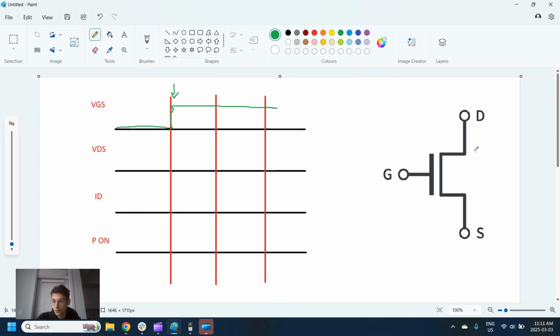And what happens? Well, our voltage here, we would love for this to drop instantly. This needs to go from whatever the VDS is down to 0, because that means a short circuit. And that means the current will also need to go from 0 up to some value and stay there constantly. If that happened, we'd have 0 power losses, but this is about power losses, so obviously that's not going to happen. The reality is, we'll start with the current here.